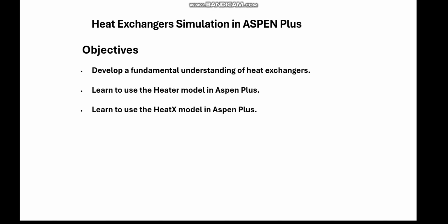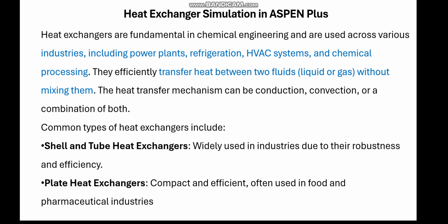In today's tutorial, we are going to simulate heat exchangers in Aspen Plus. The objective of today's lesson is that you will develop a fundamental understanding of heat exchangers, and you will know how to use the Heater model in Aspen Plus and how to use the HeatX model in Aspen Plus, and what is the difference between these models, and when we use the Heater model and when we use the HeatX model. So before going to the simulation, I will just briefly review what a heat exchanger is.